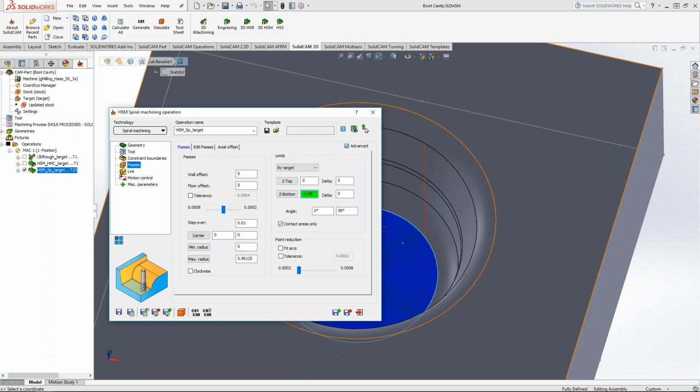If you use a flat end mill, it basically has a flat area on the bottom. You have a clearance angle on the bottom of it. Well, that clearance angle is very minimal, maybe half a degree at most. So if for some reason a chip gets hung up underneath there, it would drag across that surface and scratch it.